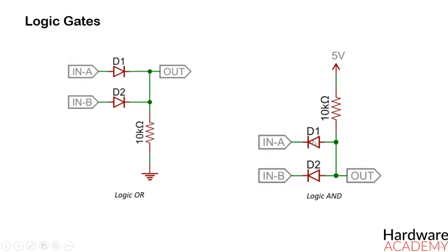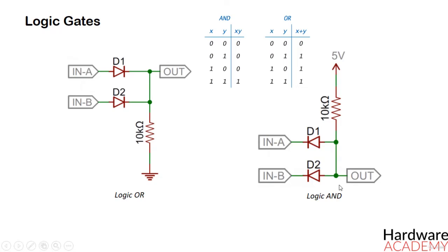An AND gate is constructed in a similar manner. The anodes of both diodes are connected together, which is where the output of the circuit is located. Both inputs must be logic 1, forcing current to run towards the output pin and pull it high also. If either of the inputs are low, current from the 5-volt supply runs through the diode.